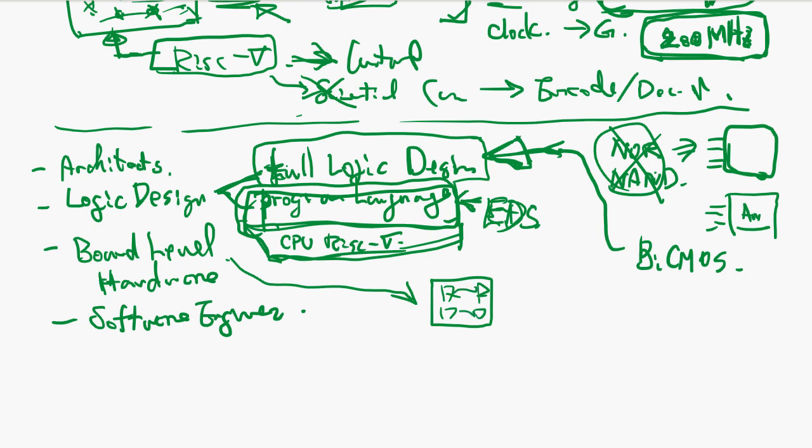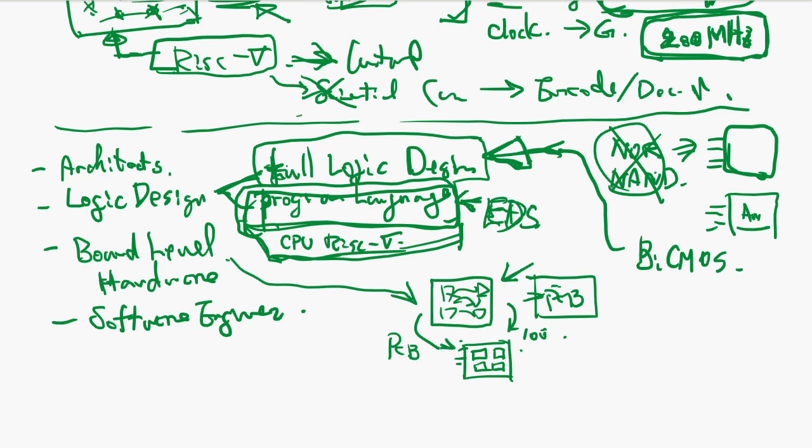This is like an interconnection design, automatically generating the interconnection files and making a PCB board. But these days, in high performance devices like a cell phone, they use a silicon chip to interconnect CPU, memory, those. So the size becomes like 100 times smaller. PCB used to be PCB. It becomes 100 times smaller because it's a silicon chip.